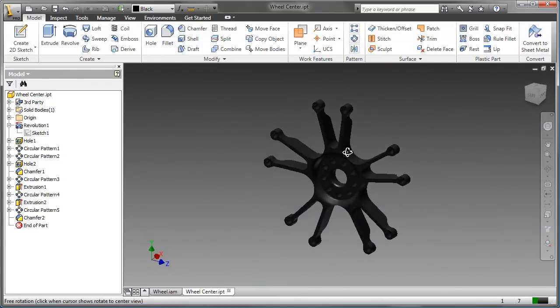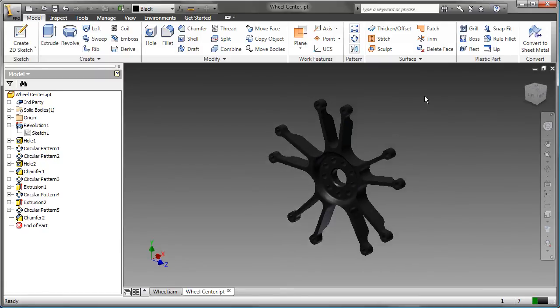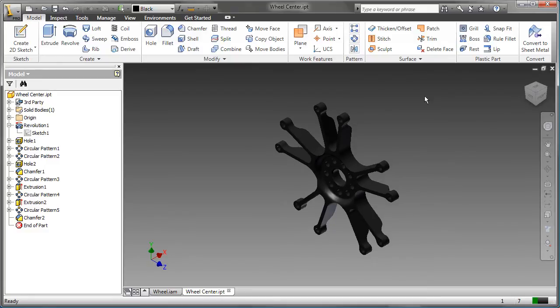In this assembly, the overall dimensions are controlled by 2 design criteria: the radius of the wheel and the diameter of the hub around the drive shaft. The stress, displacement, and safety factors are all within the design criteria. However, more meaningful reductions in the mass of the wheel center are prevented by these overall dimensions and the desire for a conservative safety factor to prevent catastrophic failure and injury.